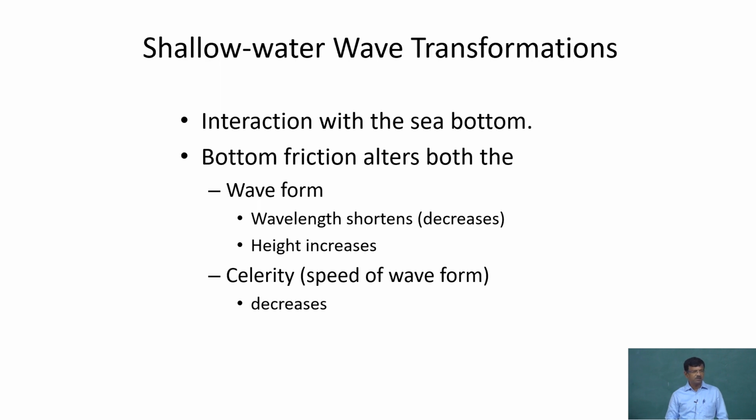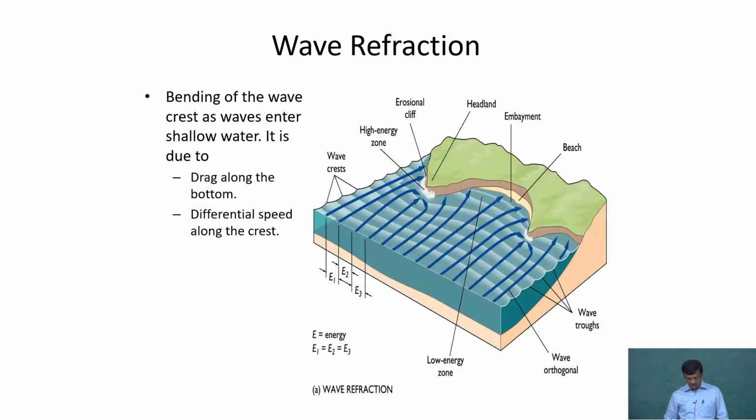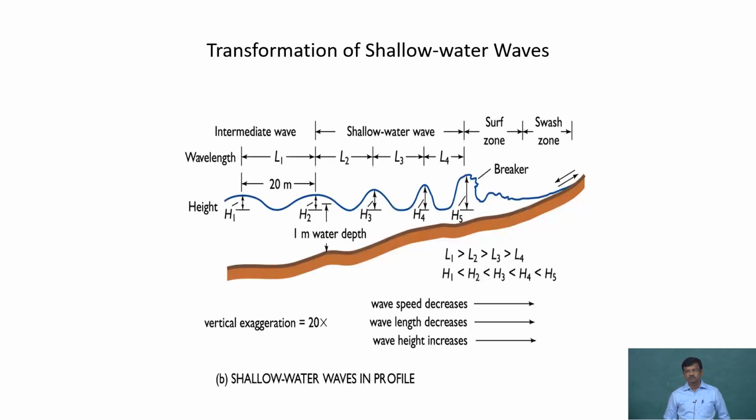Water depth dictates the speed of the wave, which is very important, as it makes the seabed drive the system. Shoaling is the increase of the wave height. A normal wave, say about 50 centimeter, toward the coast will grow to 1 meter or 2 meter, and finally it breaks. Ultimately a wave is all water particle mass. It cannot stand or pile up beyond a certain extent, so it has its own limitations. It will break after a certain depth, which is called wave breaking. This is purely based on the shoaling.